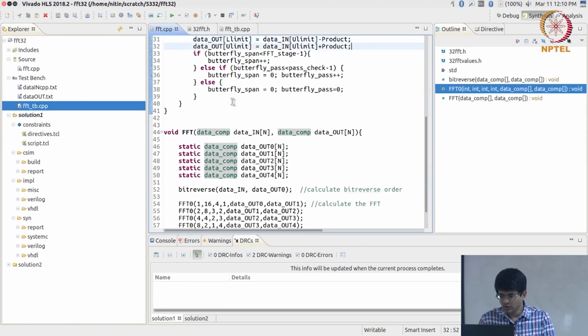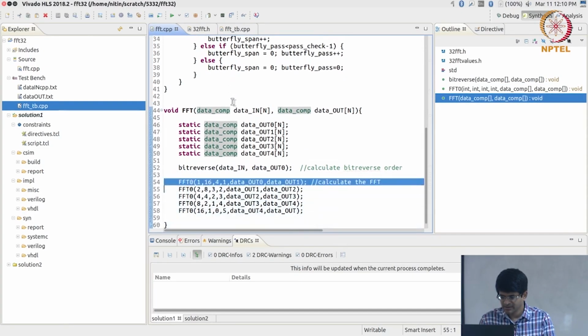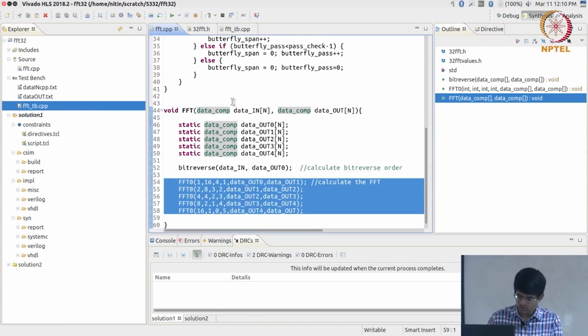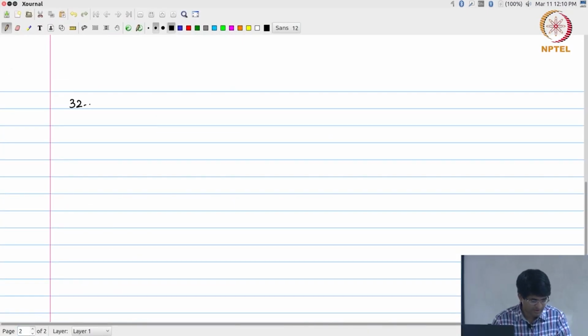The function itself looks like this, right. The important part is pretty much just these 5 stages, right. So, if you think about it, what is happening over here is we have a 32 point FFT. Okay. So, there are 32 values out here, right, 0, 1, 2 up to 31 complex values. Okay. And the computations that happen are essentially, there is some kind of cross computation involving some twiddle factors, right, the exponent of minus j2 pi k n by n.